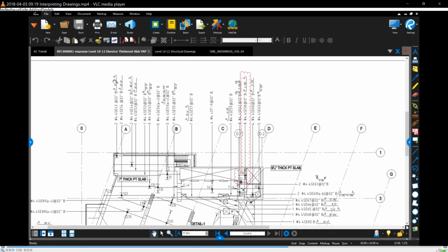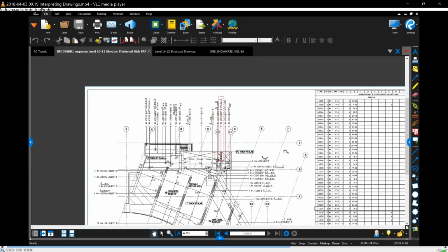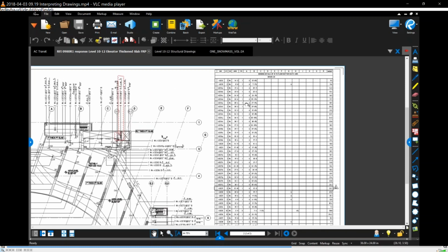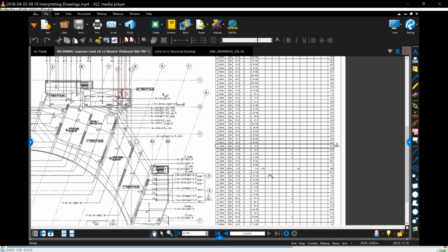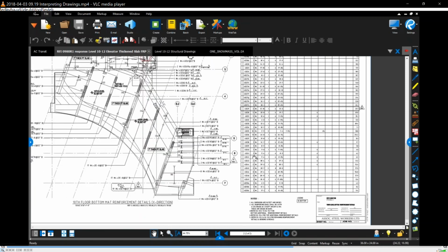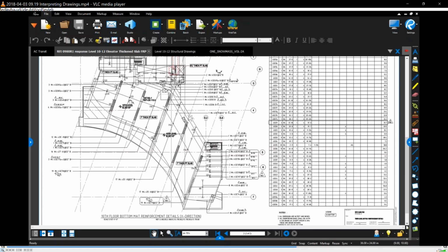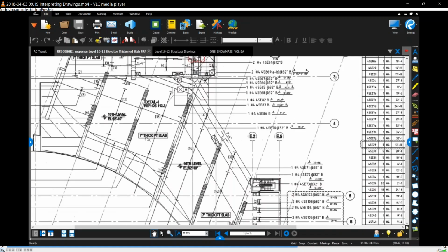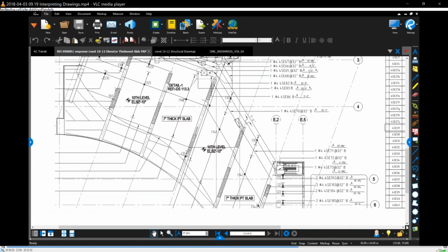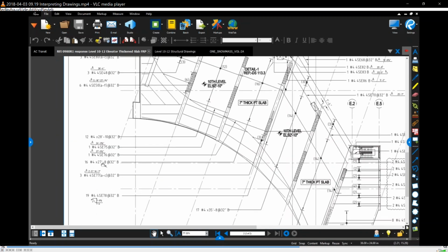They detail every piece of rebar, all the shapes, and where exactly they need to be installed. They also have a takeoff, so they can add up how much rebar material they need to provide for that project. And this is provided to the EOR, or engineer of record, to check and make sure that the rebar subcontractor got everything correct. So they have the slab thickness, and they want 16 number 4s, 27'8". Just reiterate the EOR's drawings and the rebar contract.